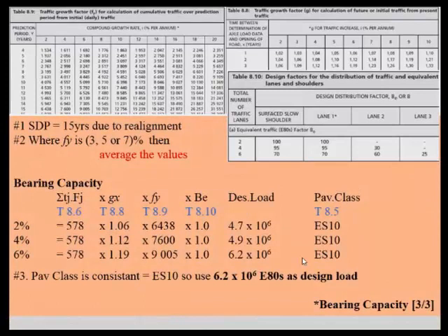The cumulative equivalent traffic bearing capacity over the structural design period of 20 years may be calculated in 3 steps. By determining a growth factor for future traffic from initial traffic. Table 8.8 demonstrates a 3-year period to opening of the road and a 6% growth rate.